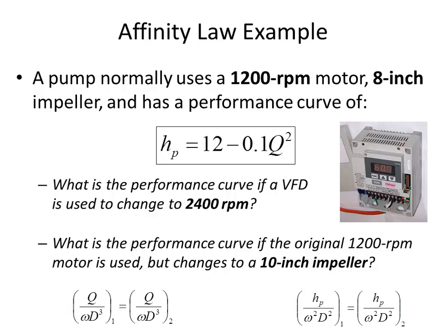We can rearrange that. Since we're not changing the diameter on this, it's the same pump, but it's just operating at a different point, we don't have to use the D term.